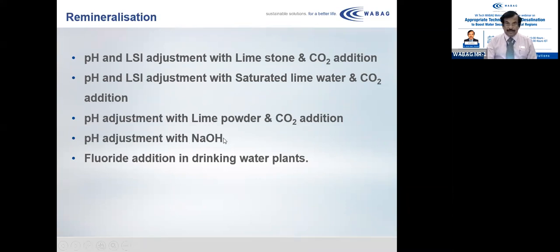pH adjustment with sodium hydroxide can also be done without any lime or CO2, but this addition is suitable for only smaller units because it slightly changes the taste when the pH level goes above 8.5.